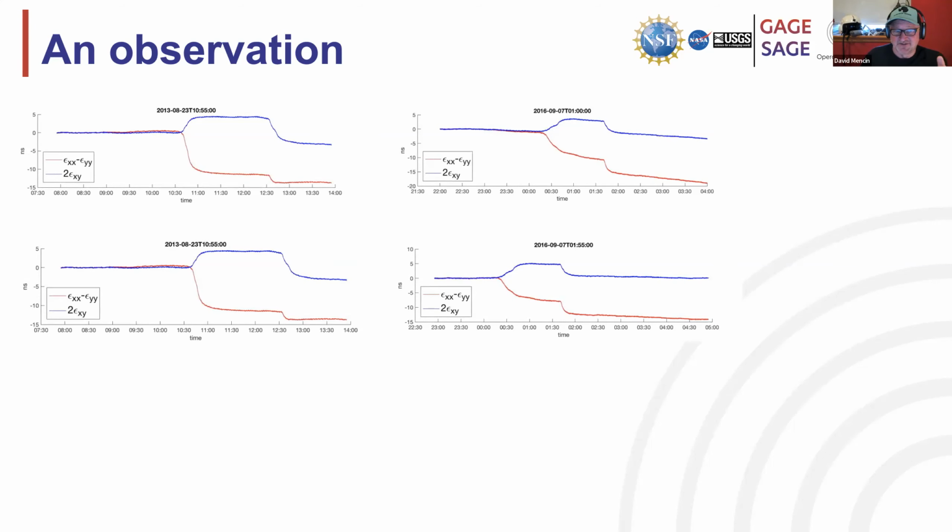This particular section of the fault has this strange behavior of starting and stopping, or we don't really know. It could be jumping some part that doesn't creep and starting to creep later on. But this is a repeatable behavior on this particular part of the fault, where a creep event starts, and it either stops and starts again, or potentially jumps some zone that isn't creeping and starts again on the other side. With one creep meter, or with one strain meter, you can't tell. If we had several strain meters, we'd be able to see all this starting and stopping behavior of these small creeping patches.